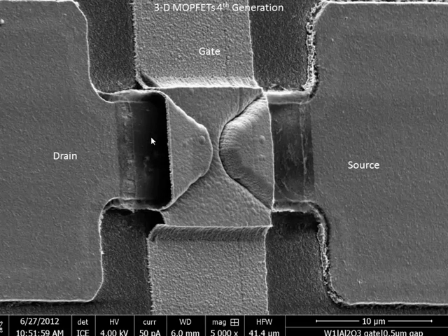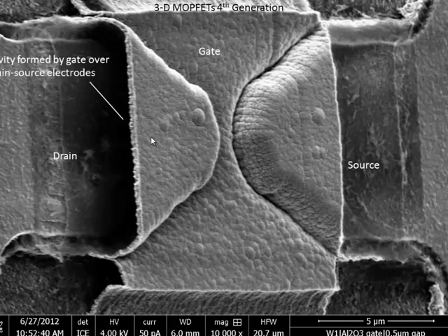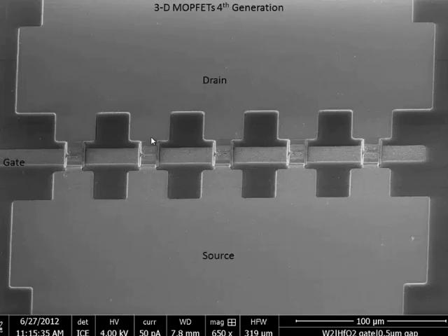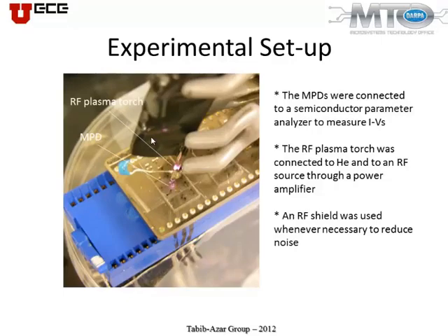These cavities are produced by xenon difluoride etching of polysilicon that is used as a sacrificial layer, and the metal gate underneath it has an ALD passivation layer so that the electrons cannot directly go through it, so it reduces the conduction for the electrons through the gate. We want the gate to be isolated as much as possible. The same concept that you have in MOSFETs based on semiconductors. So you can put these in parallel in order to increase the amount of current that you want to conduct between drain and source.